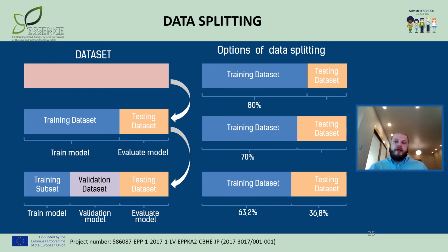And it's very important because if you will not treat the formulation of training and testing set properly, finally you will get the model which perfectly predicts sunny weather conditions, but it will never be able to predict cloudiness. And for this reason, please think about the shares of sunny, cloudy, rainy data in the training set and in the testing set to be sure that your model is able to predict photovoltaic power plant output in abnormal conditions.